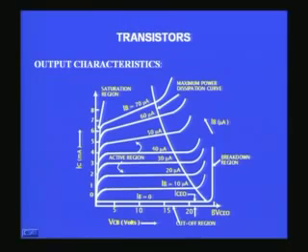Well, if IC is very small, the VCE can be very large. As we increase the IC, you would find the maximum value of VCE keeps decreasing. So it comes out something like a rectangular hyperbola, and therefore I should never make my transistor work anywhere in the region beyond this curve, which corresponds to the maximum power dissipation curve.